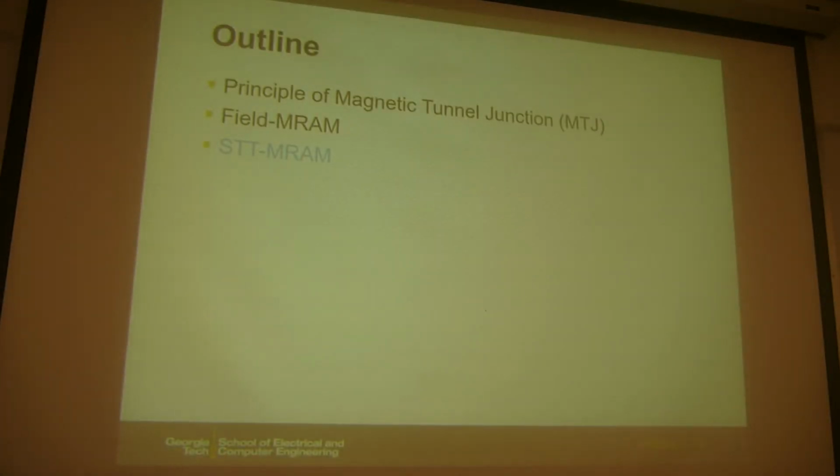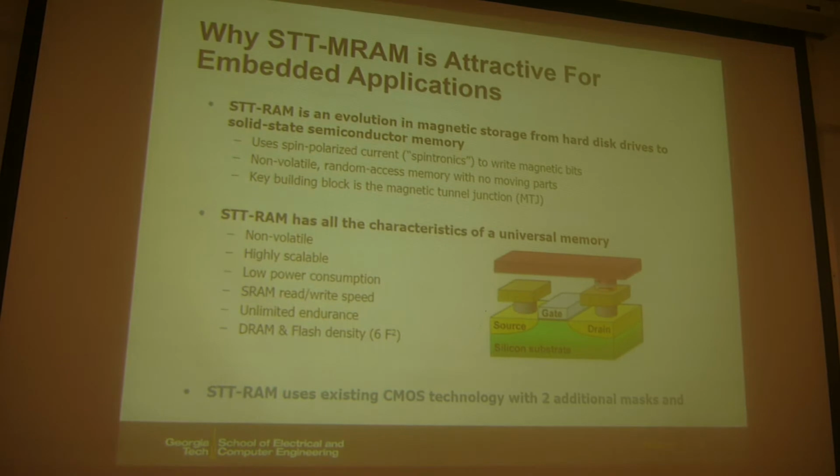Better scalability. So let's look at why STT-MRAM is more attractive. The structure is very similar to the previous RAM or phase change memory, with this 1T1R, and you can have the MTJ structure to the contact of the drain via.